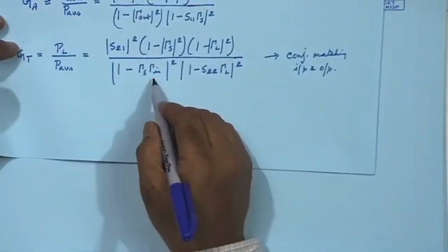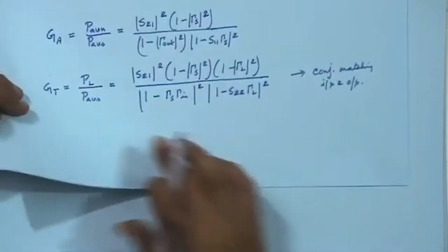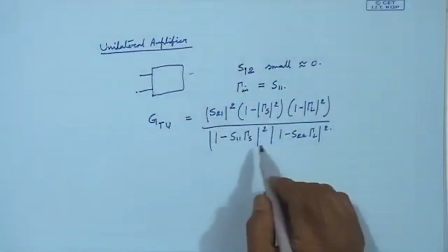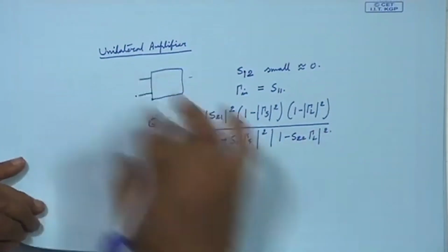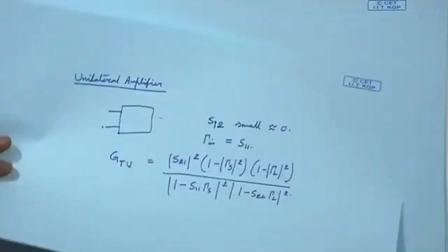These two, sorry, this input reflection coefficient. Now, here that is absent. That means for the input reflection coefficient I need to know what the loading is. Here it is independent and a much simpler design can be attempted through this. So, this is another special case that we will see in the gain definitions, that for unilateral amplifiers this simplification can be made. Now, let us generalize that now we are in a position to simplify our whole microwave transistor design.